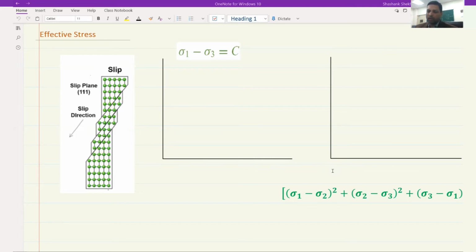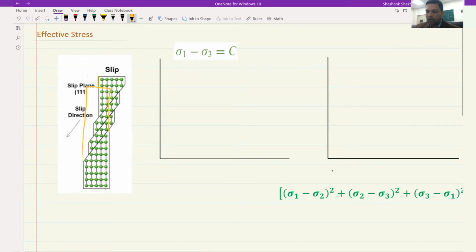So look at an example, and let's say initially you had a long bar like this. Let me draw it like this. So initially this bar was like this, and when you applied a stress like this, then there was slip occurring on different planes, and this is how the deformation occurred. So don't assume that the bonds are getting broken between layers, that complete detachment of bonds is taking place. That is not correct. What is actually happening is that some kind of defect, which we will explain in a couple of lectures, called a dislocation,